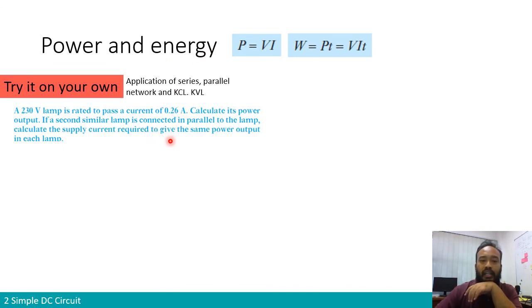And then finally, of course, when you do KVL, you can also calculate the power, just like last week. When you have calculated all the voltages or all the currents in your circuit, you can also calculate the power. For example, the power supplied by a power supply is the voltage multiplied by the current supplied, and the energy or work produced by that power supply is the power multiplied by how much time you are delivering that power. If we expand P into V multiplied by I, it becomes VIT. We have done this last week, so it's the same thing.